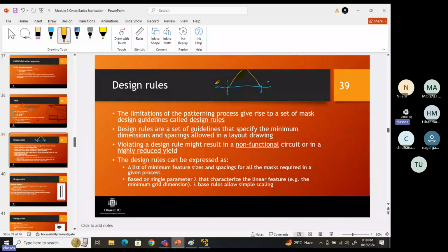Okay, so what are the kinds of DRC you can see? You can say interval spacing related DRC, then edge to edge spacing, then dimension related spacing, then corner to corner, vertex to vertex spacing. Then you can tell some examples like n-well to n-well spacing should be this, m1 width actually, m2 to m2 spacing, then implant to implant spacing, oxide to implant spacing. These are the kinds of spacing which you can find in the design rule. Then via spacings, then via enclosure size.